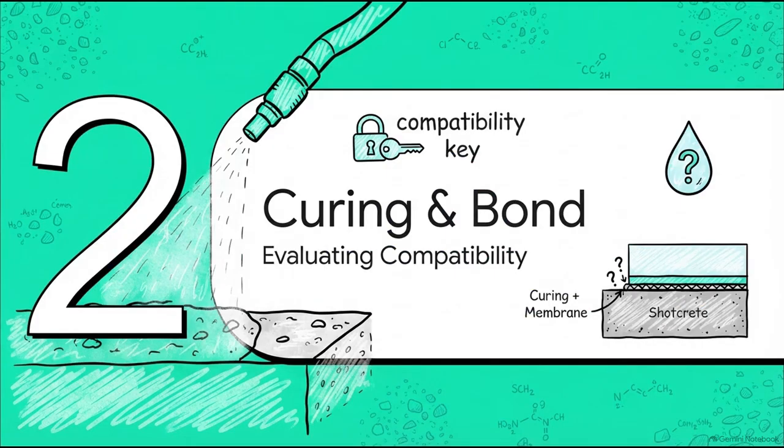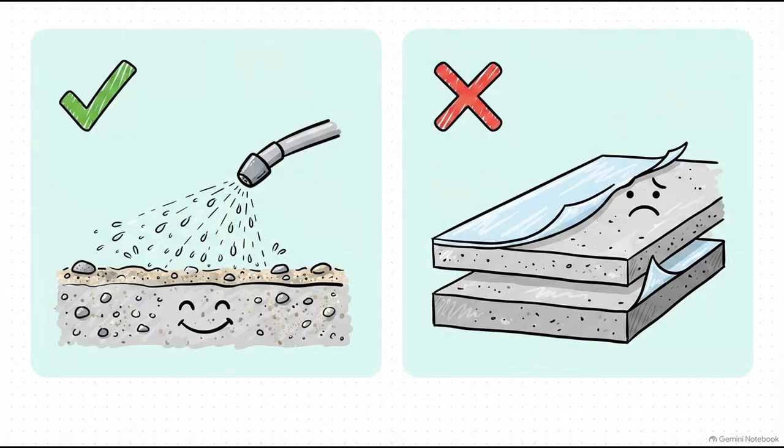Moving on to Section 2, let's see how this whole concept shifts when we introduce curing compounds into the mix, and why evaluating compatibility is a game changer. Curing compounds are fantastic for moisture retention on a completed final surface. We love them for that. But if more shotcrete is coming later, certain compounds are a massive red flag.